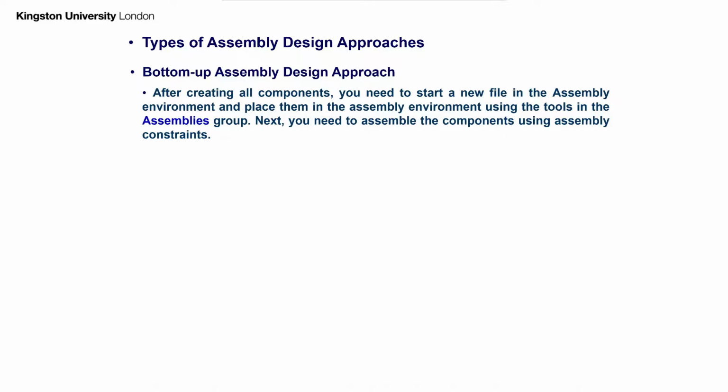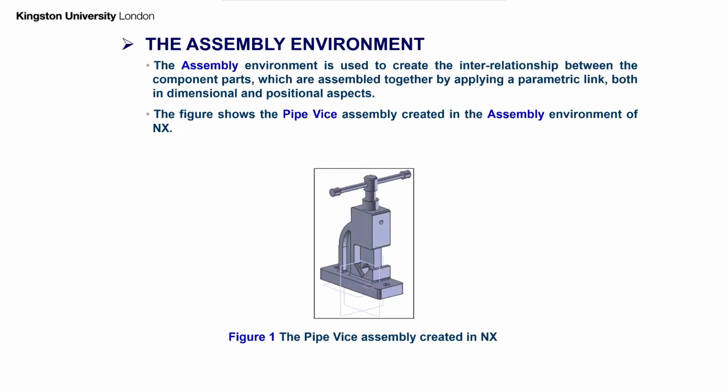Usually, in order to decide which of these methods you're going to go for, it depends on what part you would be able to fix as the first component and then use as a reference, or also what part would have the bigger size that you can easily fix and continue. For instance, the model that I just showed you here, it's better to go with the bottom-up technique, because basically this component I can consider as a first component, fix it, use it as a reference, and the rest will have the relation based on the first reference.